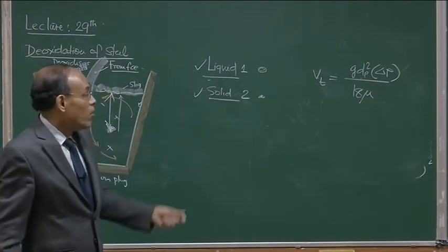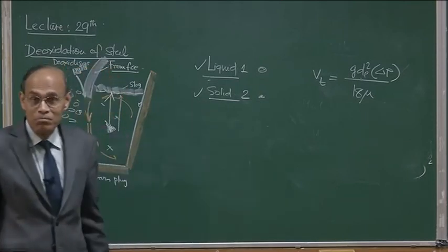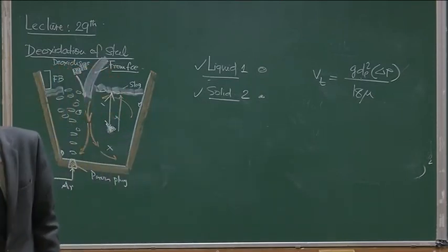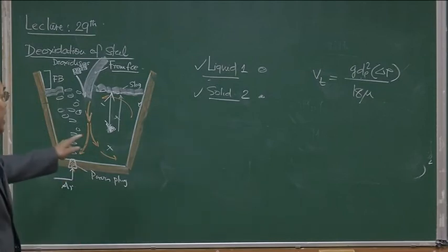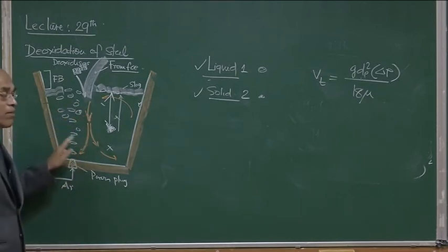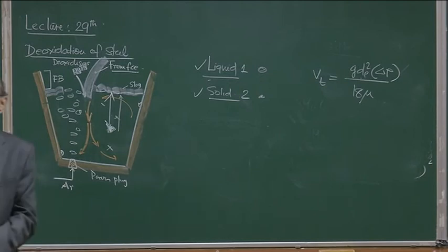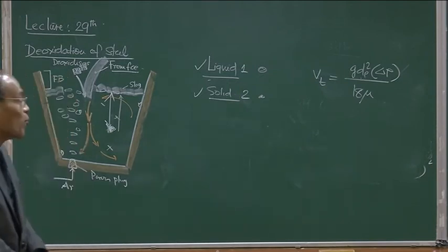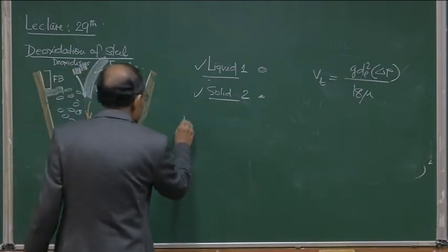That is why if you use 100% aluminum as deoxidizer, there is a good possibility that a lot of alumina particles may remain entrapped in steel. The entrapment of deoxidation product contributes to what is known as inclusions in steel.